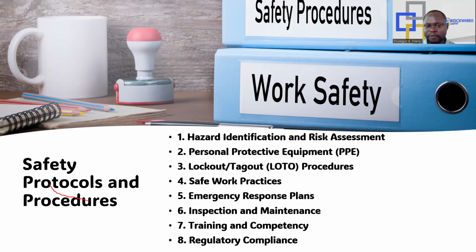And there's what we call the HAZOP, H-A-Z-O-P. This simply means hazard and operability study. It's just the mixture of hazard and operation, and we call it HAZOP. Then we have what we call the FMEA, failure modes and effects analysis, to identify hazards. You can use that also to identify hazards in power generation, and then involve multidisciplinary teams in risk assessment to ensure comprehensive coverage. Now, you cannot do it alone. Don't forget, you cannot do it alone.